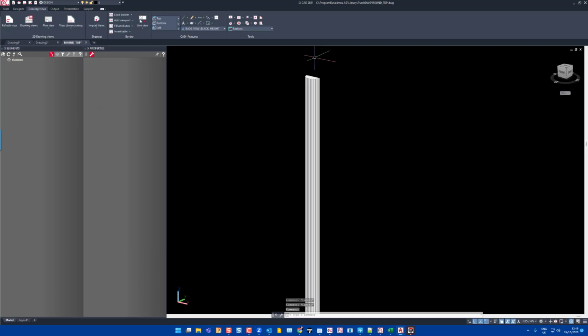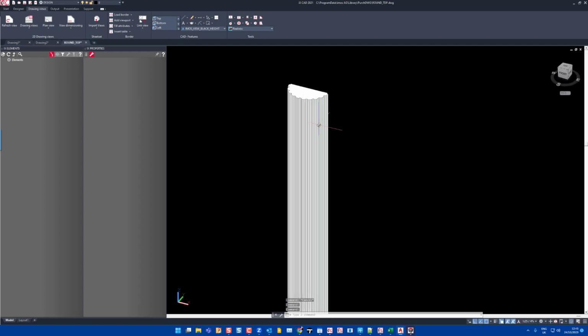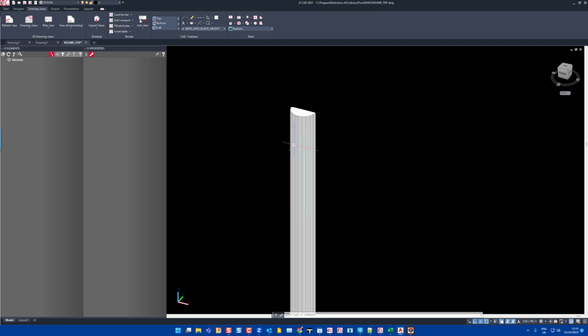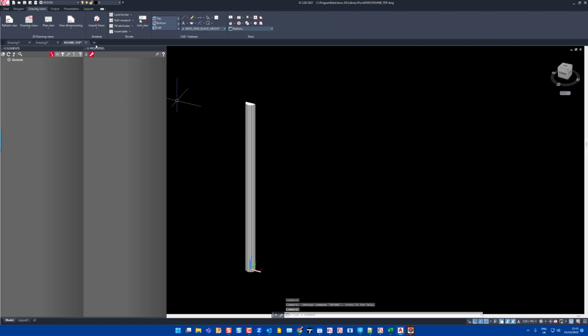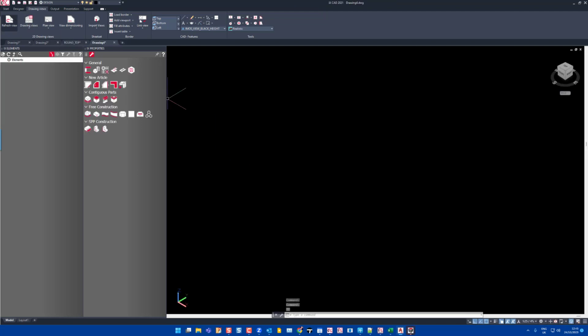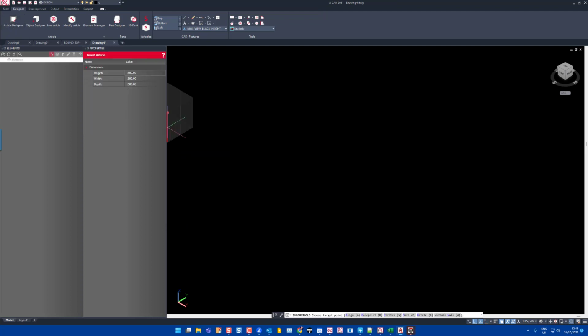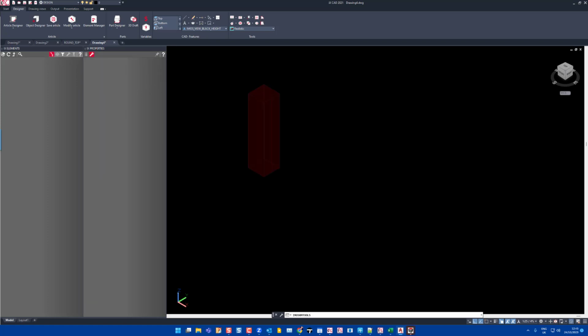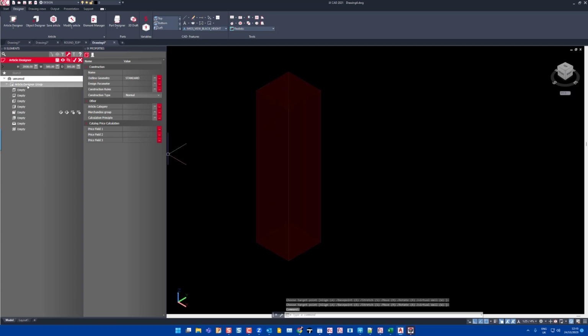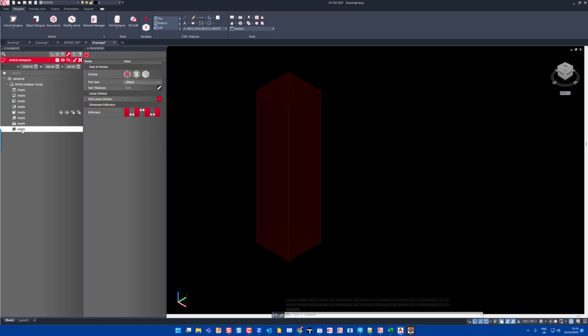Now what I want to do is, now that I've made my 3 pieces of timber or wood or decorative moulding or whatever you call these things, I want to combine them together. So what I'm going to do is come into my product and say article designer in here. This is going to be a height of 2 meters, width 500 by 500. This is fine. And then in here, what I want is a linear division, and I'm going to say that that should be 100 mil to 100 mil.